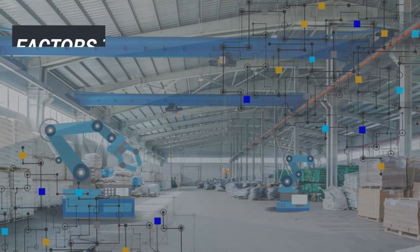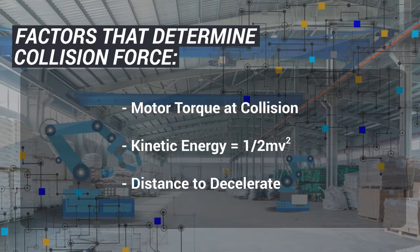There are three major factors that determine collision forces. These are the motor torque applied during the collision, the kinetic energy of the robot, and the distance to decelerate. For many robots, during a collision, the motor torque will spike to its maximum as the path tracking error suddenly increases.